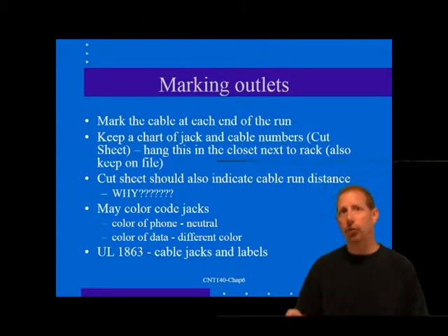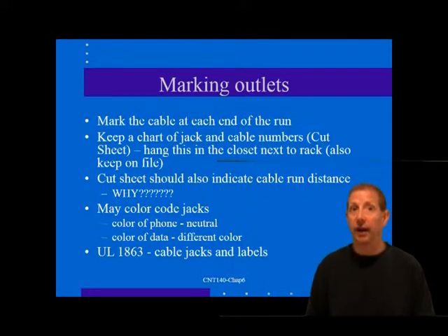So if we talk about workmanship, the subject of workmanship is particularly important with regard to jack termination. The higher categories of wiring have strict guidelines for the amount of untwist that may be present at any point of termination. When a pair of wires is untwisted, even slightly, it can cause a greater disruption to the high bandwidth signal transmission than almost any other non-continuity defect. Furthermore, there are several points of unavoidable untwist in any cable, and the effects of untwist are somewhat additive.